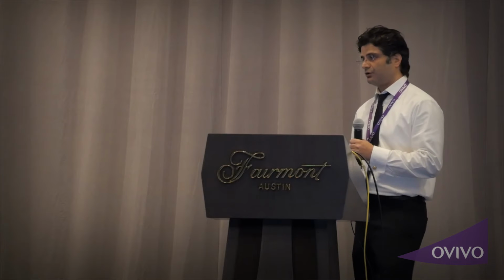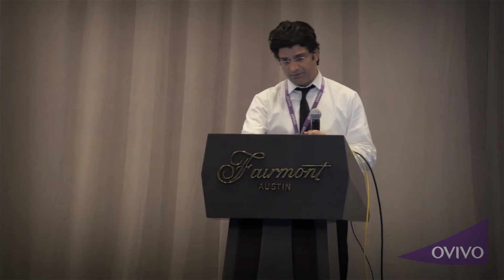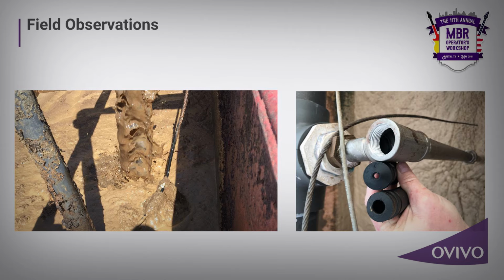One of the important key factors in an MBR system also, as my colleague explained earlier, is screening. Proper screening is very important. So in this plant, as we see, we had screen bypassing, and I'm going to go through the picture. Screen bypassing could cause clogging or equipment failure or compromise the equipment performance. So those are all critical factors you need to consider. Here, as you can see on the left side, there is a cable and big ragging hanging off the cable, which is due to bypassing the screen and causing issues.